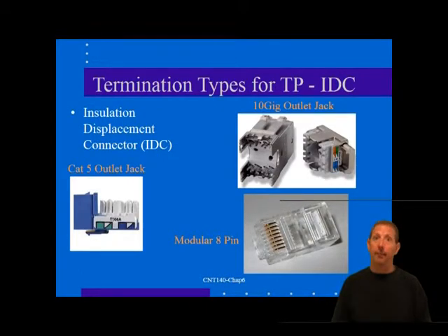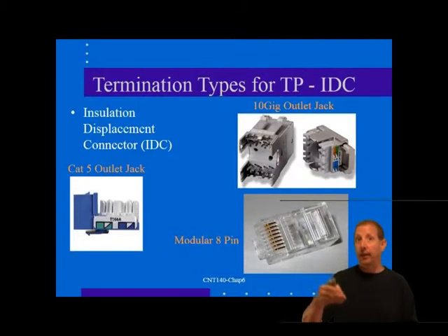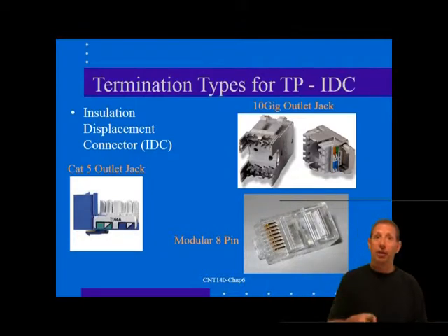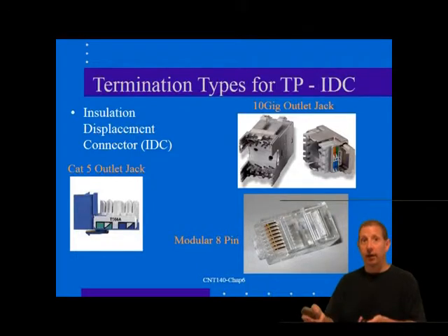In this jack type, the wires of the modular connector are connected to positions on the block into which the wires from the station cable are then punched. The amount of untwisted wire from the block to the connector is usually too great for this type of jack to be certified above Category 4, if indeed it is certified at all.